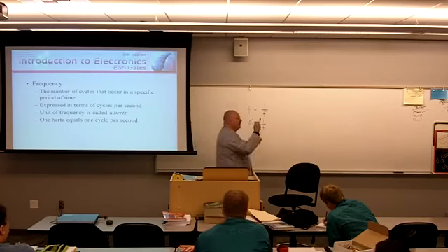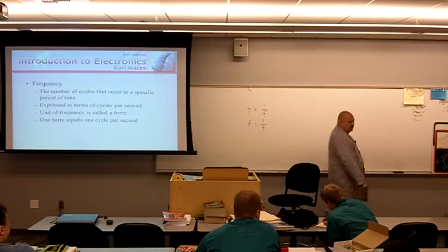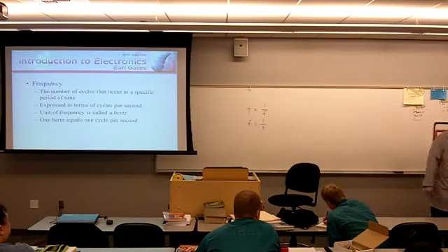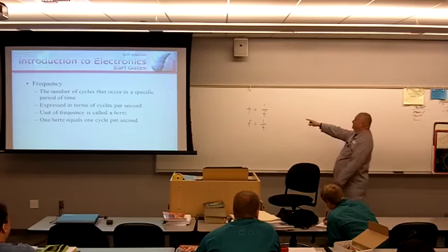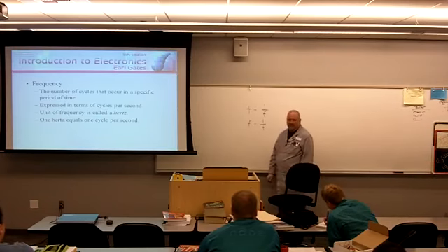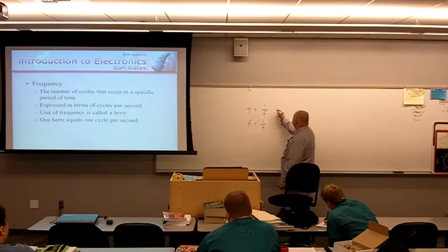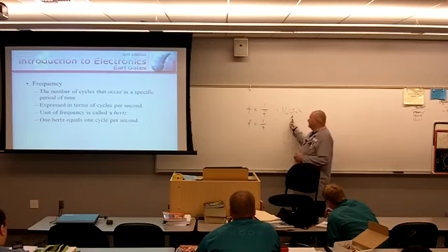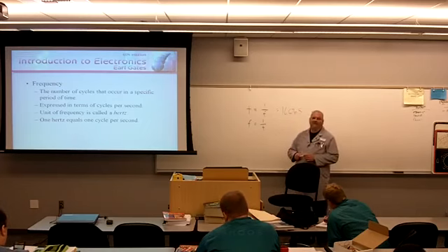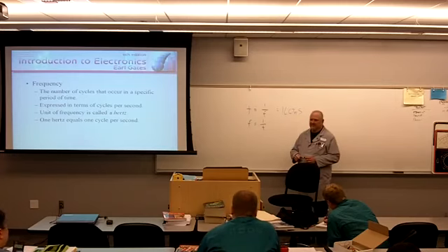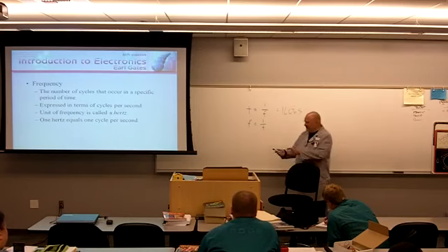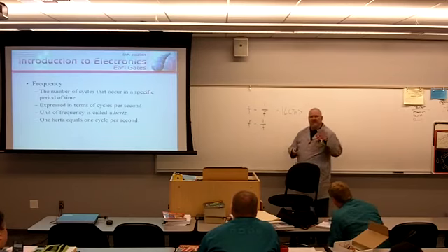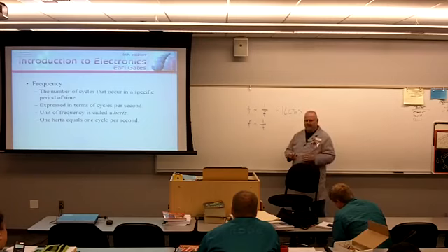So, what comes out of our wall here as far as frequency? 60 hertz, okay? Plug this in the formula right there. 1 divided by 60, what do you come up with? Give it to me in proper terms, please. That's how I roll. It's kind of my thing. 16.67 milliseconds. A sine wave that comes out of the wall repeats itself every 16.67 milliseconds.